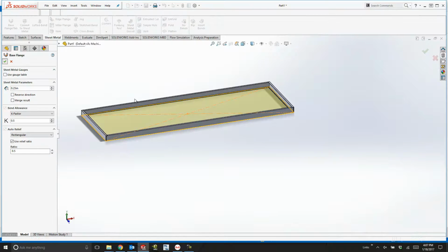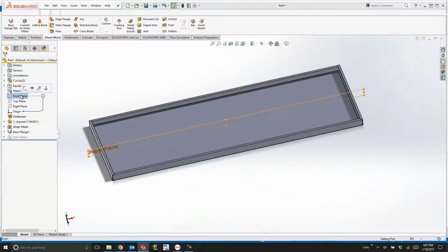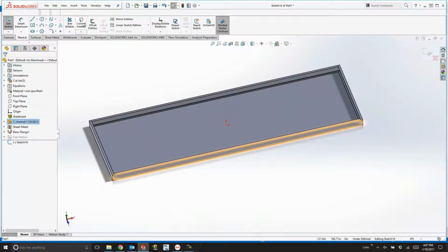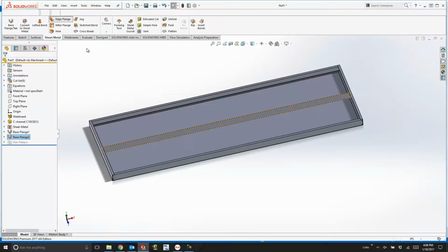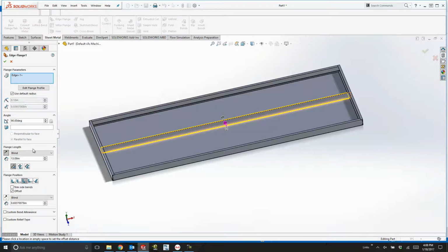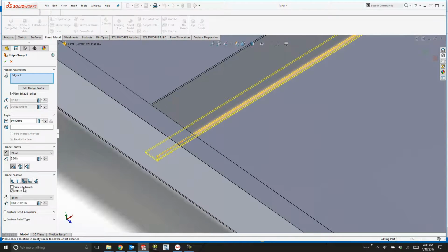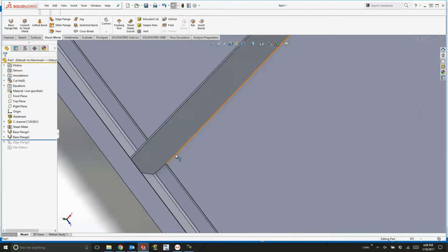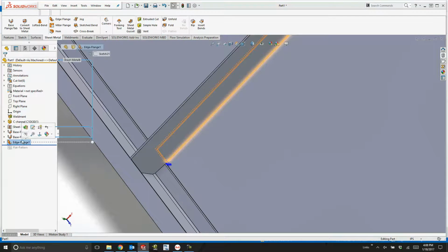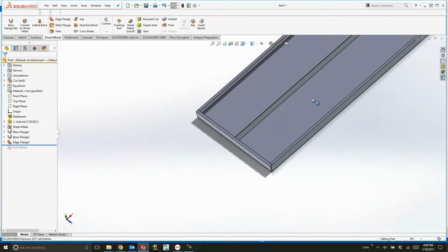A base flange feature with the exact same sketch gives me a nice flat platform on the bottom. I can split that up if I need to for manufacturing purposes. But the next thing I'll do is take that coped shape, just reuse that coping shape to create a base flange in the middle of the part on the front plane. Use an edge flange at the bottom, set the material condition to material inside with no offset, and it's going to do a really nice job of creating that flange at the bottom that will allow me to connect to the bottom face with no gap in that.